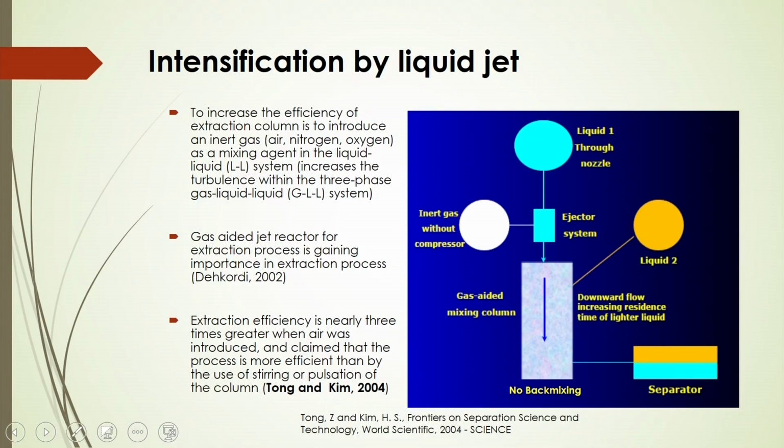Another important intensification of the extraction is called the liquid jet based extraction process. In this case, whenever the liquid jet plunges into the pool of liquid, the two immiscible liquids give you finer droplets, and getting more finer droplets means getting more interfacial area.